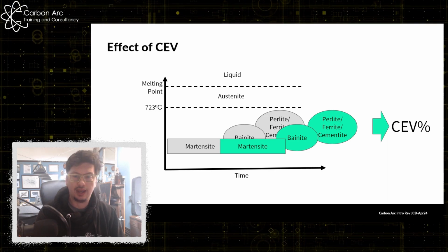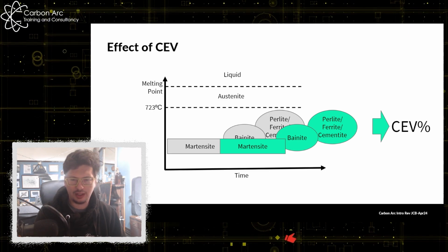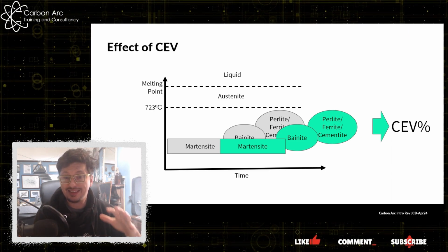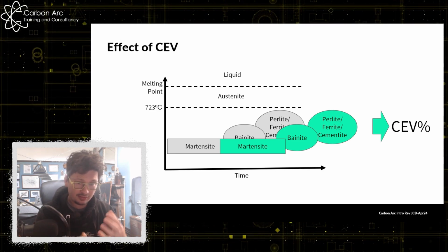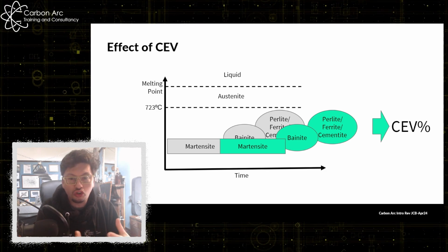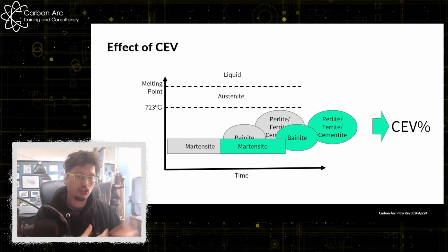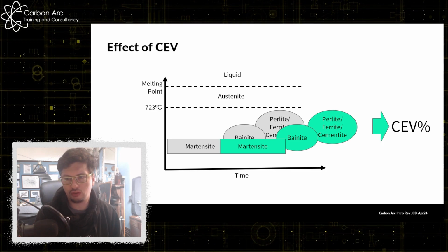Yeah, and we're going to come to preheats in a future video, and around a standard called EN 1011. 1011 is a great standard if you want to know, generally good control within welding. 1011-1 has general rules, and then 1011-2 is also a good one to pull into.